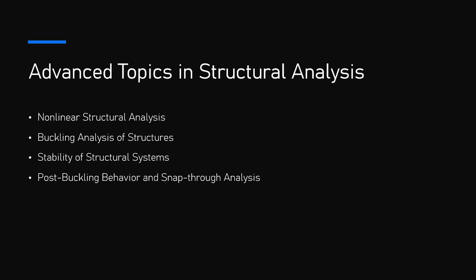prevent failure. Pushover analysis. This method involves applying a monotonically increasing lateral load to a structure until it reaches a predefined displacement, which helps engineers assess the structure's capacity to resist seismic forces. 2. Buckling and instabilities. Buckling analysis in columns, frames, or shells requires nonlinear analysis, as the structure can undergo large deformations before buckling occurs. Nonlinear models help predict the critical load at which buckling happens and simulate the post-buckling behavior.